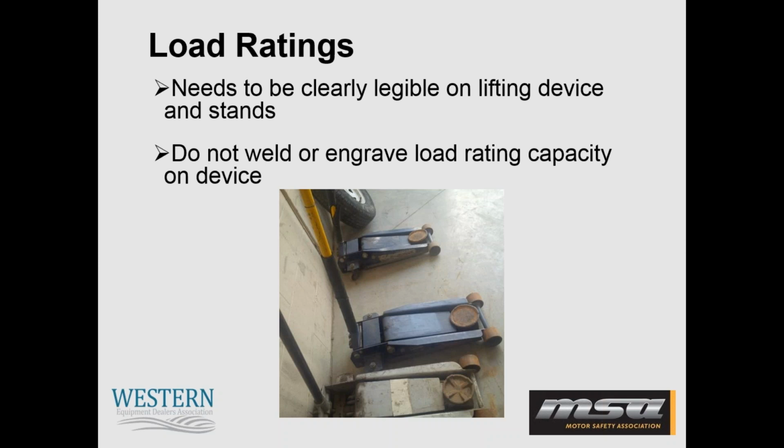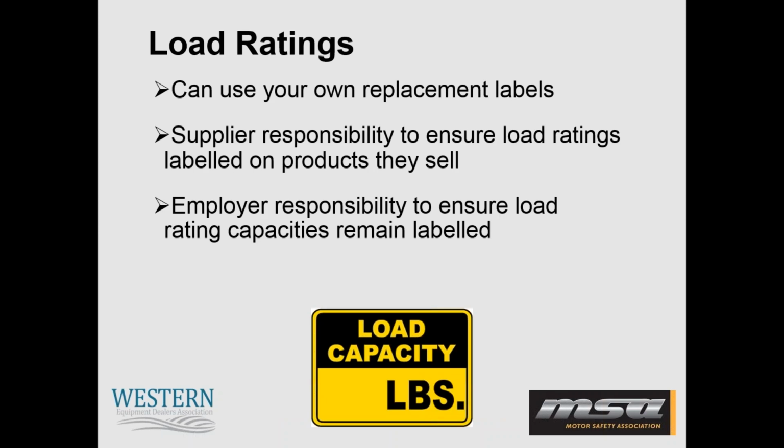So don't do that. And if you're in a situation where your labels have come off of your jacks, such as in this picture, you can use your own replacement labels. If you have a label maker, you can use it to put the labels onto your lifting devices. And in some situations, those stickers just don't like to stick.